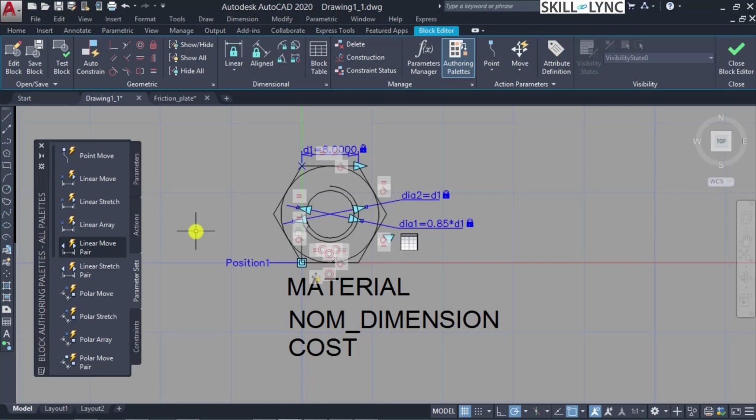And always we have to associate the action with a parameter, a key point on the parameter on the geometry. So a key point is the point on a parameter that drives its associated action when edited. So it means that this point we have associated to this key position. So this is what is going to control the action of it.